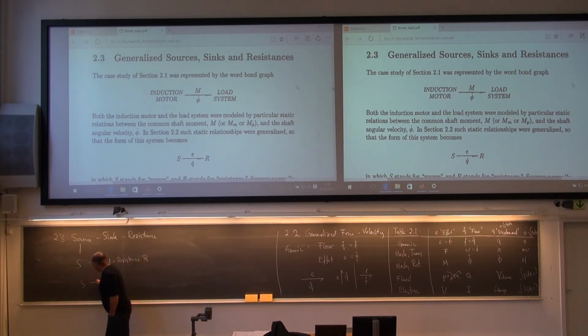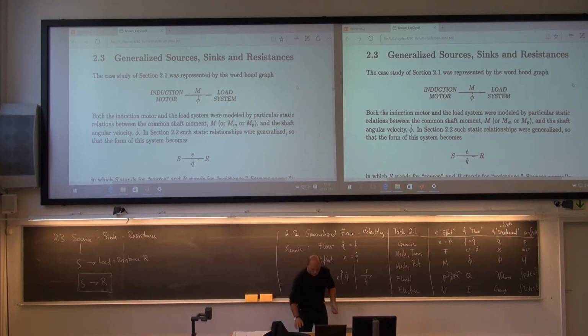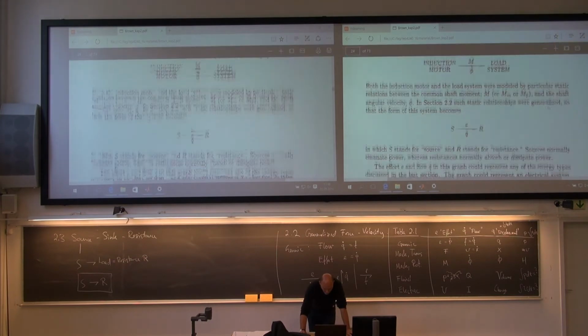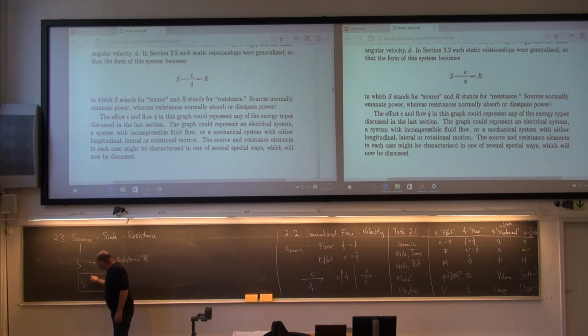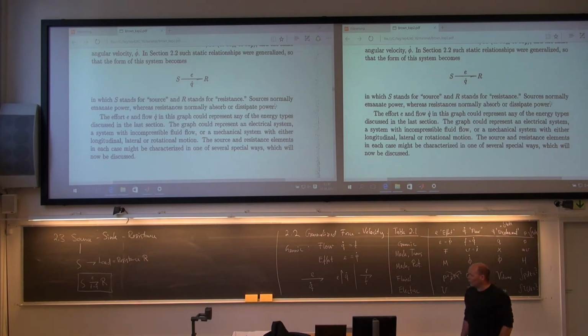So our bond graph should actually have looked something like this for the example with the water sprinkler. And as you see, effort on top and flow under. So normally you don't even write these, e here and an f down here, or a q dot as the book likes to do it. You don't need to, because you know they are there anyway. Effort and flow.